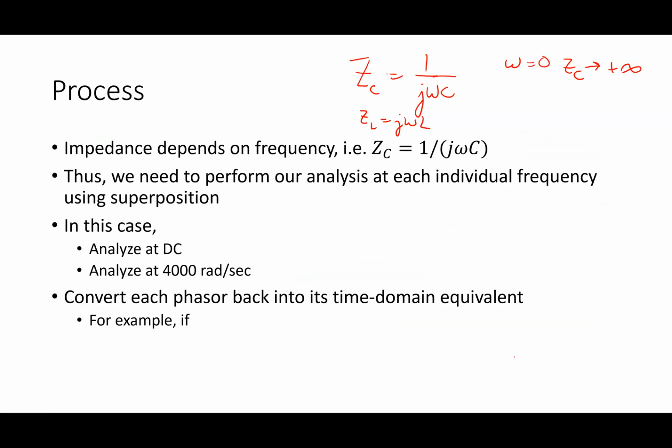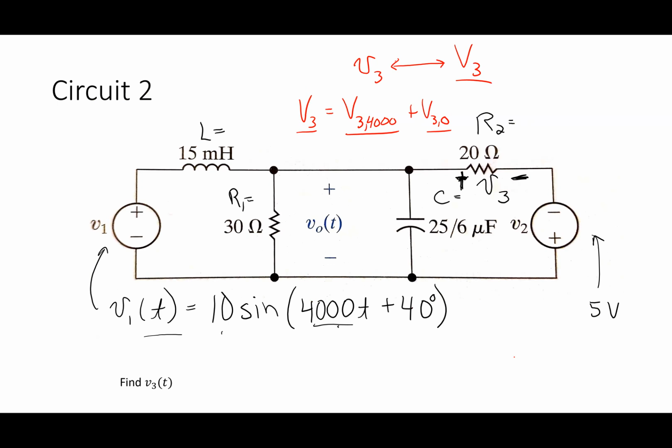Short the other one. And more generally, because I'm trying to be pedantic, I'll turn it off, right? Which works into being, because I turn off the other sources. Turning off a voltage source means its voltage goes to 0. A device that has a voltage of 0 basically is a short circuit. All right. So I turn that guy off.